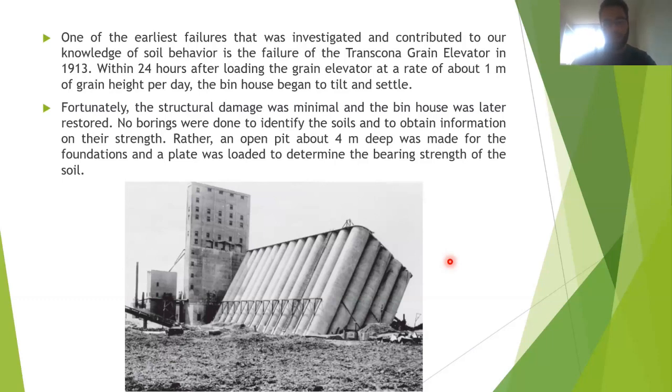And in general, you would do it for most structures. But you need to have a feel to know where you are geologically, and whether there is a chance that you have an aggressive soil. And then you can actually tell the investor, okay, I have a concern that this may be aggressive, and we need to do tests so we can protect our concrete and protect our structure. And also have a feeling about soil mechanical properties, because there's a possibility it will swell or it will shrink.